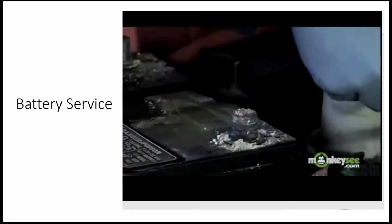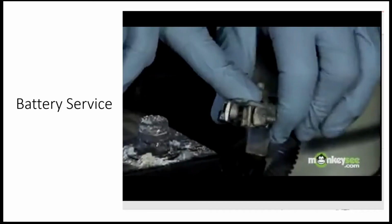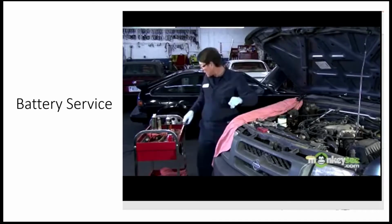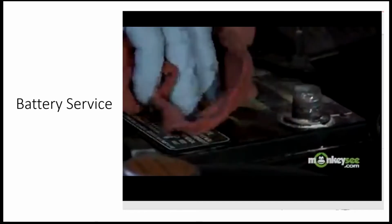All right, now we've got our terminals removed. We can see that there's corrosion inside the terminal, which we couldn't see before, but we knew there was going to be something based on what we saw around. So again, we're going to move the cable away so it can't make any accidental contact, and we're going to work on cleaning the battery posts themselves. First thing we're going to do, take a rag and clean off the excess.